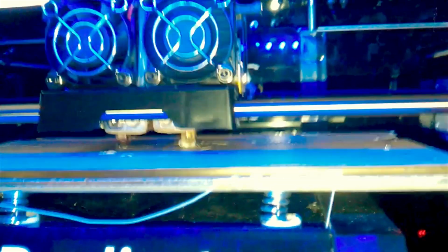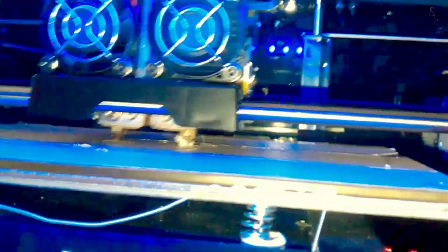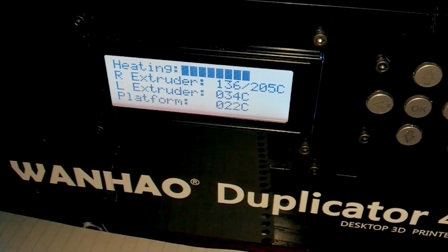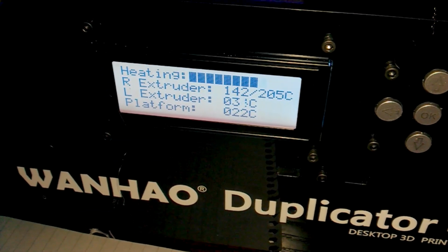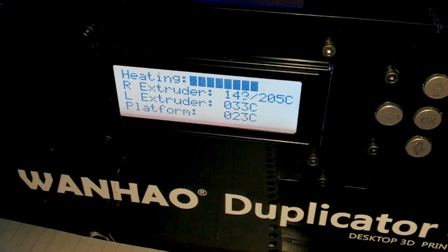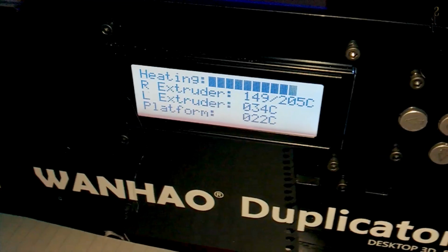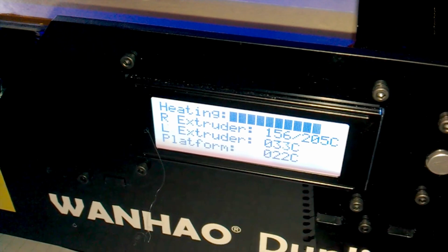And you can see there's a problem here because the build plate isn't completely leveled. The height, to be more precise, isn't quite right. So you can see it's just not sticking. So trying again, it's just coming back up to temperature. I've adjusted the build plate again. I think it's fairly level, but the height was probably not quite right.